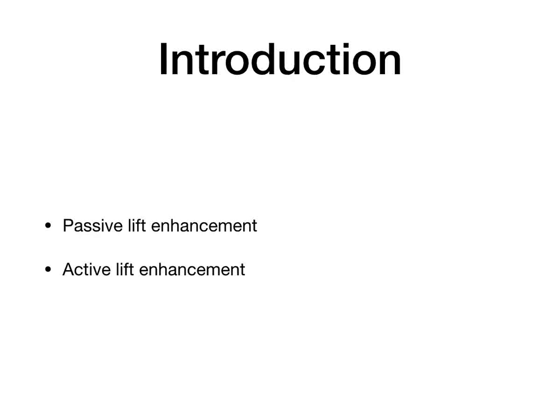The goal is to achieve necessary maximum lift coefficient values in order to satisfy the maximum lift requirements that are imposed by such flight phases as takeoff, landing, and maximum maneuverability, that is during combat.